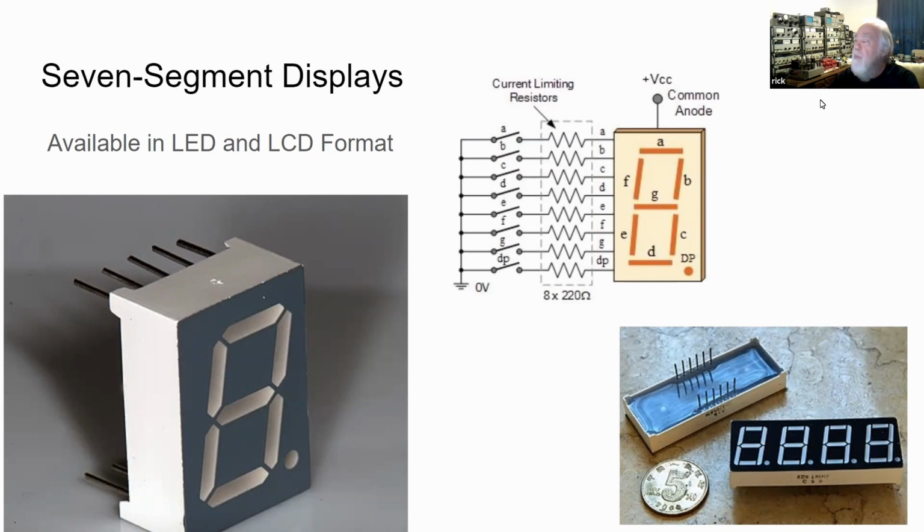Then it will change what it puts on the segment display wires to the next digit, and then light that segment and move across and display all 4 of them in sequence at about 30 or 40 times a second. So if you're doing it 30 times a second and you have 4 segments, it's actually writing 120 different values to these segments each time it displays, 30 times a second.